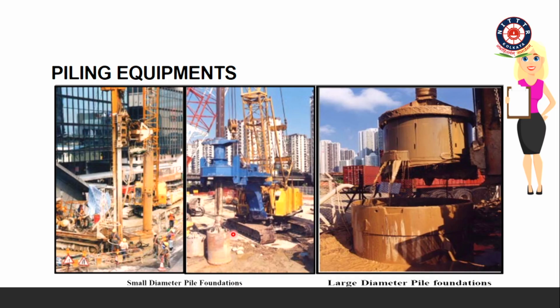As we already know, in the current scenario we are using pile foundation for metro projects. First we should understand the diameter. The maximum we are using in metro foundations is 1.2 meter diameter. Initially we were using a maximum of 600 to 700 mm for residential buildings. Because of these metro projects we went up to 1.2 diameter, and we have also constructed a monopile in Bangalore near Chinnaswamy Stadium. So in that case, this is the diameter of the borehole, and this is the casing.